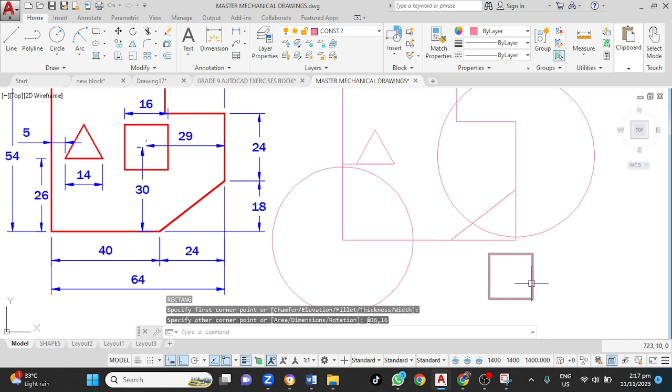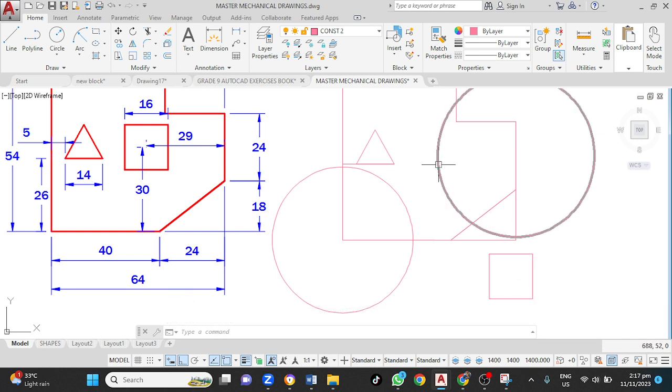That is now my rectangle. Now I intend to move this to the quadrant here. And it is important to note that when you're setting up your drawing space, you must ensure that quadrant is active. What that does, it allows me to snap onto a point right here,